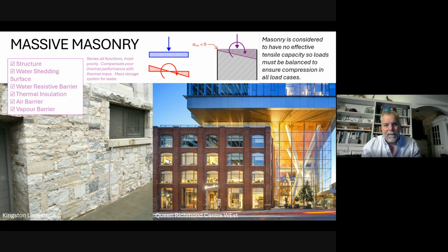We do want to continue to lose a little bit of heat through that wall. We want just enough heat to continue the vapor migration to the outside so that the wall dries. We don't want the exterior wall at outdoor air temperature, where the moisture that it gets from the rain is going to freeze and cause spalling of the brick and things.